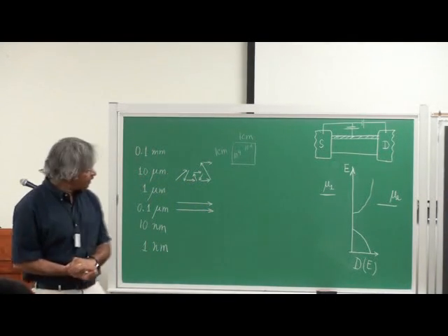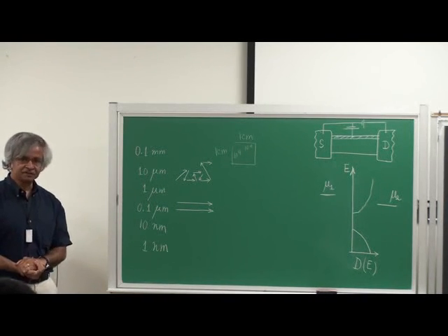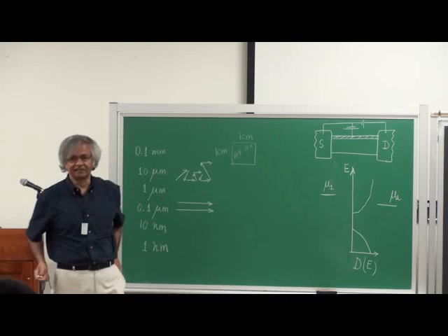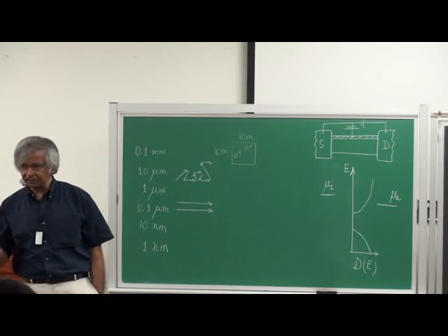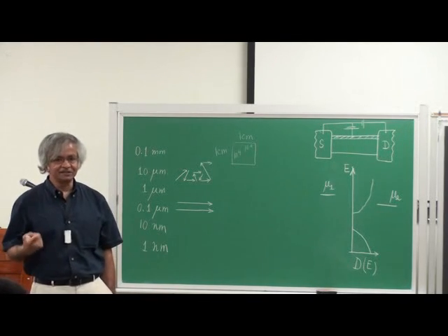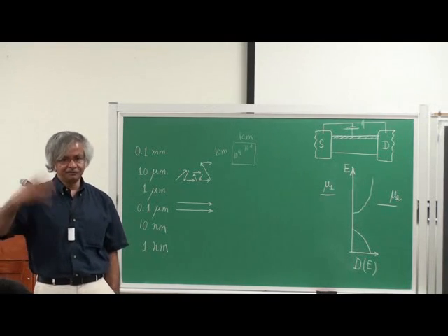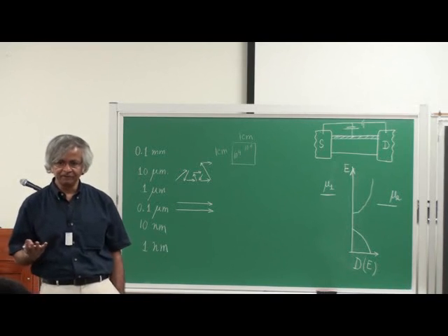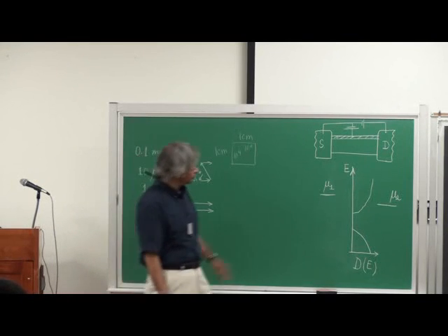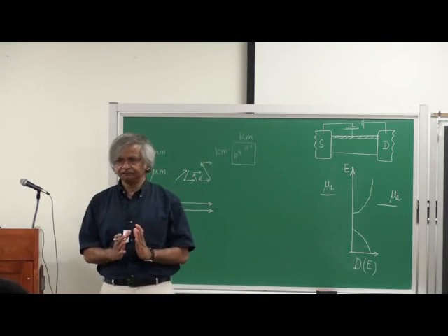Okay. Now, at this time, people say that one of the biggest problems to trying to make it even smaller is the power dissipation. Because anybody who uses a laptop knows how hot it feels. It dissipates about 100 watts or so. And it's hard to put in any more transistors or run them any faster without increasing that. That 100 watts is kind of at a limit anyway. And so, in general, there's a lot of interest in trying to find an alternative switch which wouldn't dissipate as much as the standard CMOS switch.